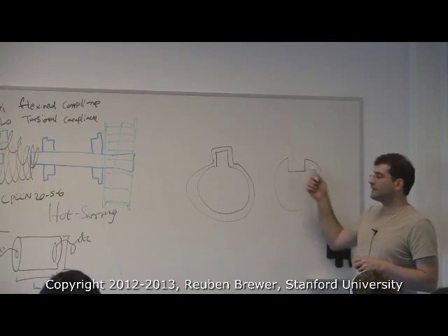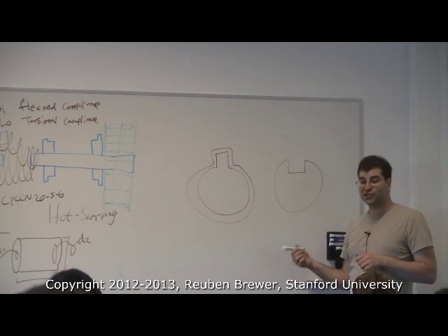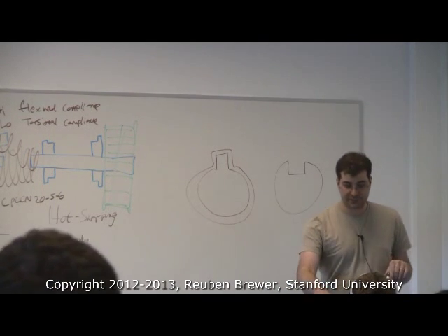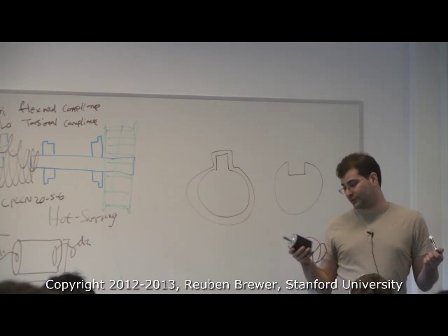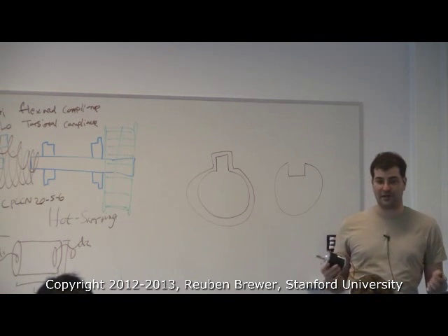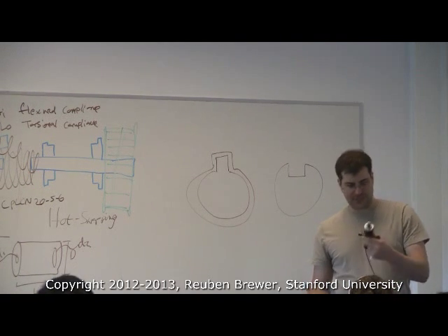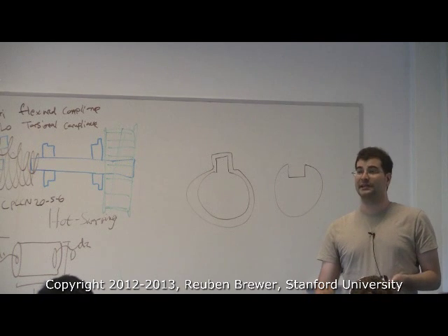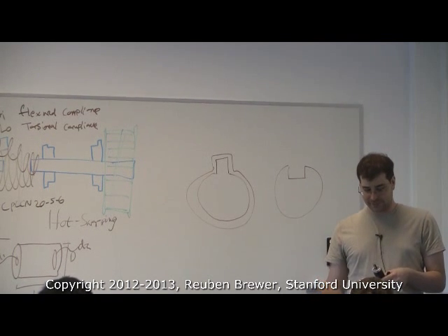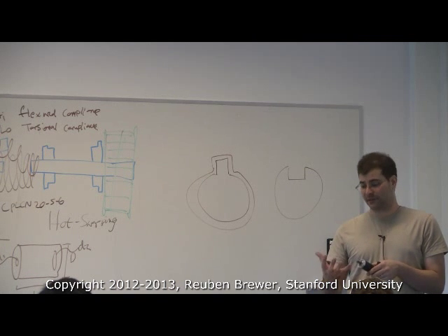They can be pretty tricky to get that key in and out. They're for super high torque. So this motor is a scooter motor, so that's probably like a 150 watt scooter motor. These are gigantic gear heads. That's why we're using keys, because to build a clamp that could take that torque would be like the size of my hand.